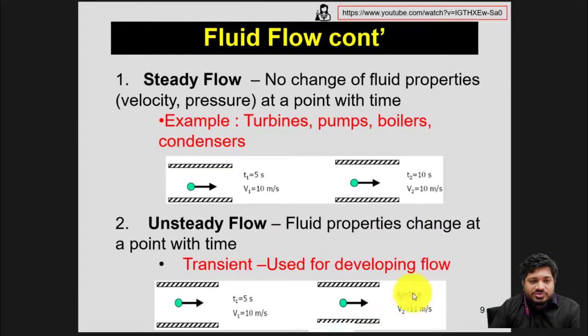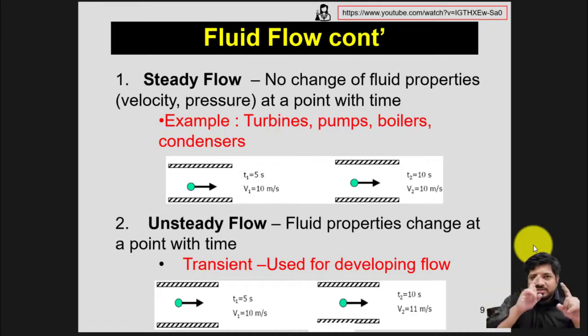If we move on to steady and unsteady flow, a steady flow is one in which the conditions of velocity, pressure, and cross section may differ from point to point. So from one point to another, the velocity, pressure, and cross section may differ, but they will not change with time. The velocity from point 1 to point 2 remains the same, but the cross-sectional area was changing. However, the velocity remained the same.